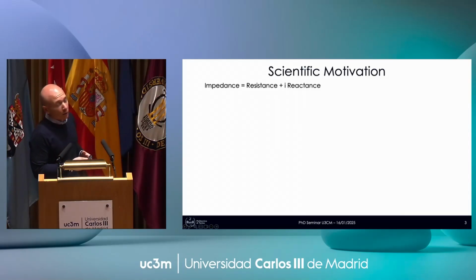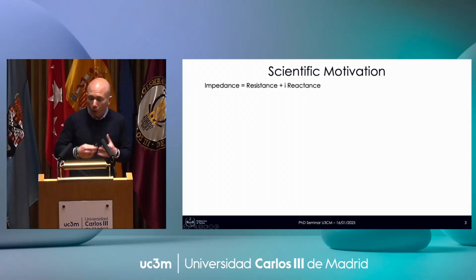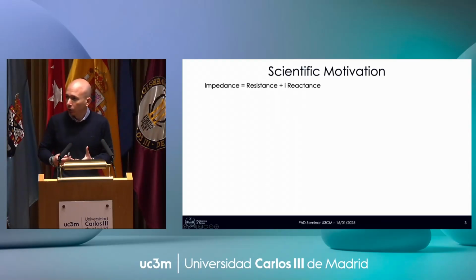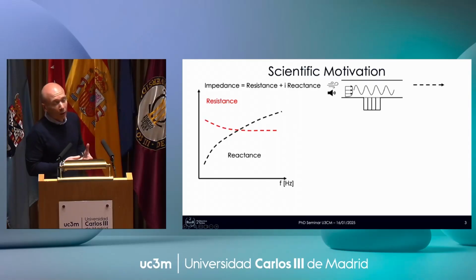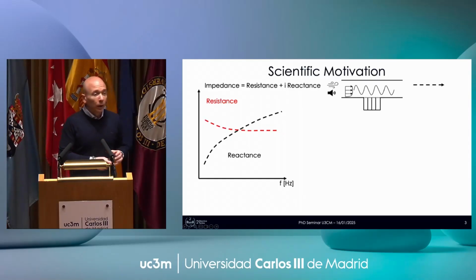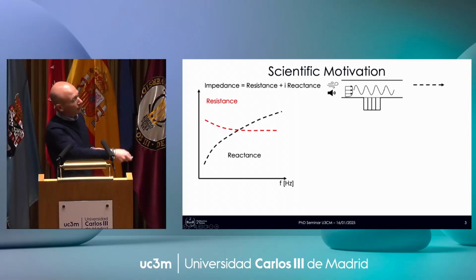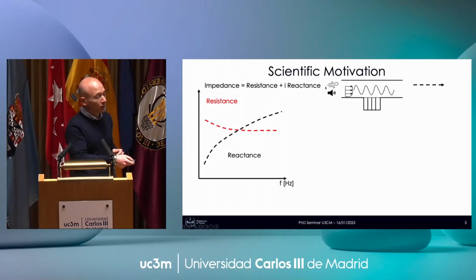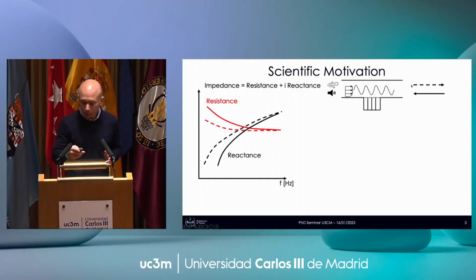How do we measure impedance? We want a quantity that is representative of the liner independently of the acoustic field on top. So what we do is use a kind of wind tunnel. We have the liner on the bottom, like you can see here in the figure. Then we have flow, in this case from the left to the right. We have acoustic sources. These can be placed on the left and move in the same direction as the flow, or, ideally, like it could be in an experiment, can be placed on the right and move in the direction opposite to the flow.